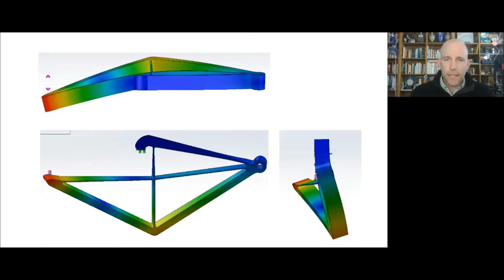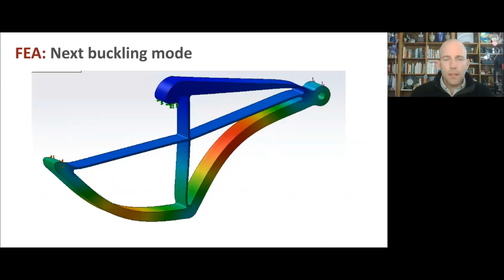And as I was tuning these things, I was playing back and forth between two buckling modes. So this is the dominant one, but in order to maximize resistance to this buckling mode, you want to make all these elements short and wide into the page. But eventually, if you do that, you run into this buckling mode where it's buckling in the plane. And this is more similar to what we're accustomed to seeing when we think about buckling, where these compressed elements are sort of popping out in the middle. So by this cross section, I iteratively selected a reasonable balance between these things.